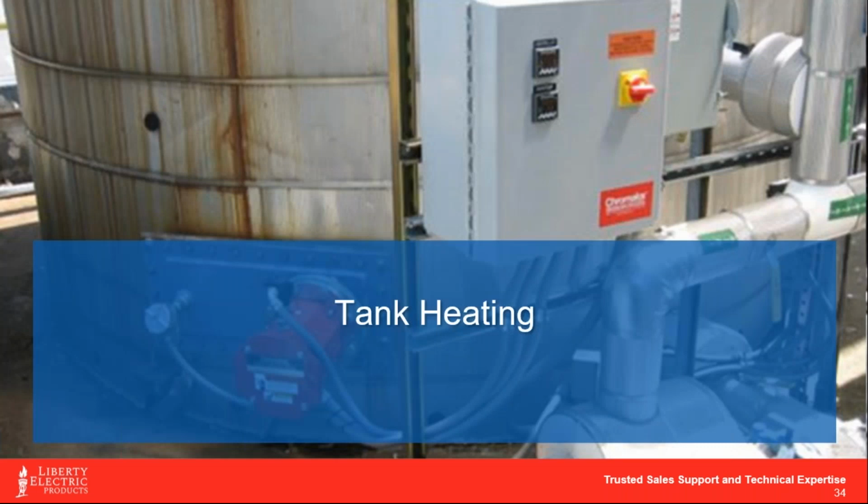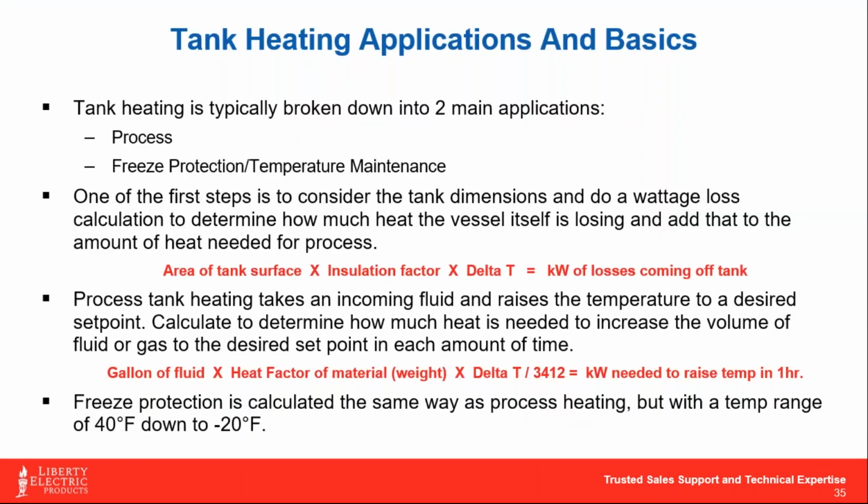All right, tank heating. This is probably the most popular of our industrial applications. And for anybody who needs it, please just type it into the comments, and we can get you these formulas or something for helping you to do tank heating calculations. But there's two different types that we do, and it's either process heating or a freeze protection application. What we do typically is take the dimensions of the tank to start off with, and we do a heat loss calculation, because obviously the bigger that tank is, the more heat the skin of it's going to emit. So we have to compensate for that before we can start really changing the temperature of anything that's inside of it. But in changing that temperature, there's a couple ways that we can look at it.